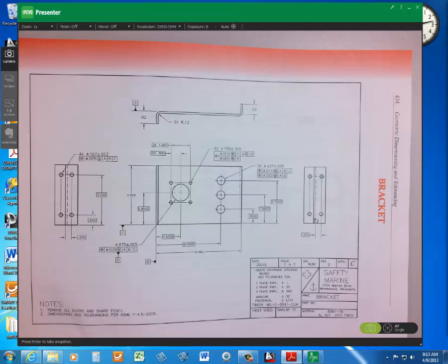All right? So, composite positional tolerance has to be mentioned. Your upper part is at 10 thousandths MMC. The lower feature control frame specifies feature relating positional tolerance at 2 thousandths relative to A, and the feature relating zone is free to shift. The feature relating zone, 2 thousandths, is allowed to shift within the boundaries of the pattern locating zone. The feature axis must be within the boundaries of both zones. Okay, the axis.